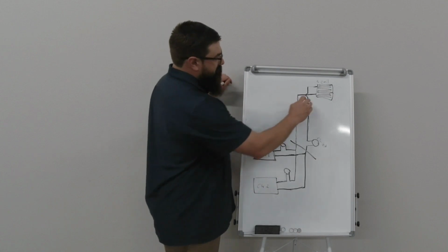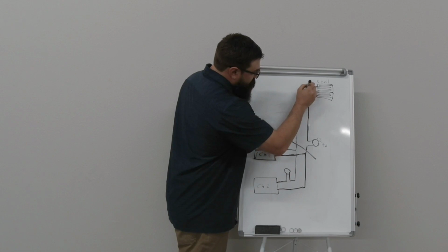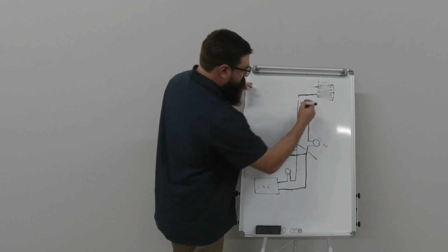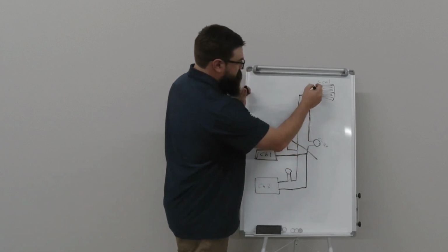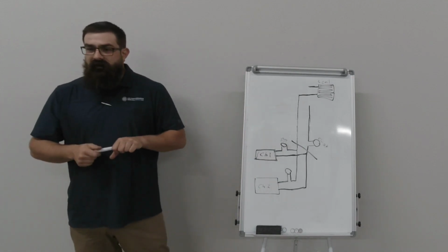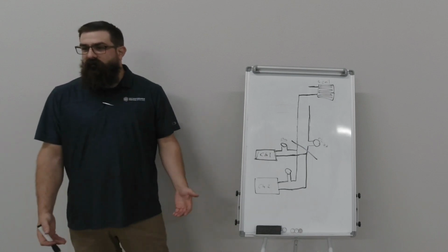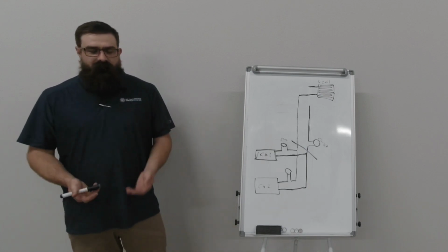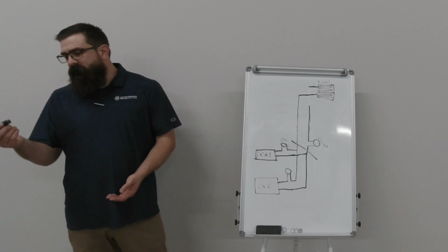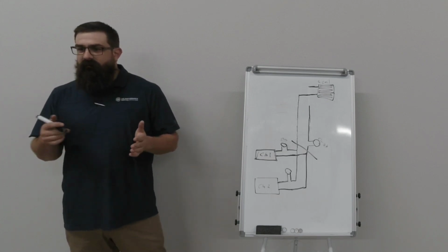So one of the things in a chill water system is we have to maintain a certain amount of flow or pressure across stuff for it to work. Like each coil has a pressure rating. So it needs 12 PSI across the coil. So that's, does 12 sound right? Okay. So it wants to see a difference in pressure on that.